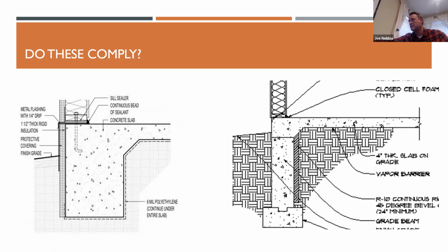And it has a direct thermal path across the slab and out. It's going to be conducted out. So this insulation, really, they shouldn't even put it in, because it's not actually performing any function. It's just costing money. So if the code requires slab edge insulation, it does need to come to the top of the slab edge in order to create that thermal break.